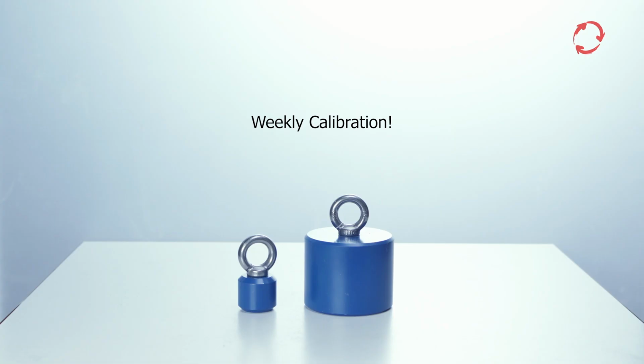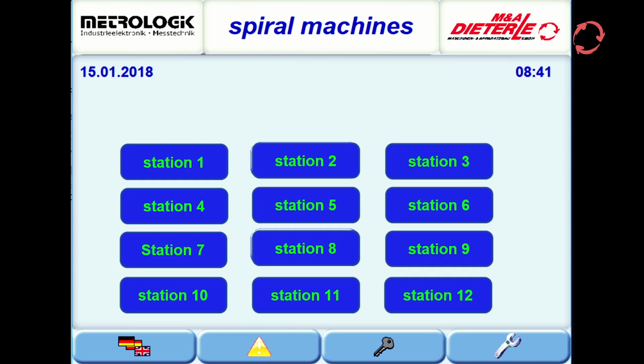One small and one large calibrating weight, approximately 500 grams and 5,000 grams, with a hook at the top, are needed for calibrating the thread tension sensors. The 500 gram weight is for calibrating the 10 Newton sensors, and the 5,000 gram weight is for the 60 Newton sensors.